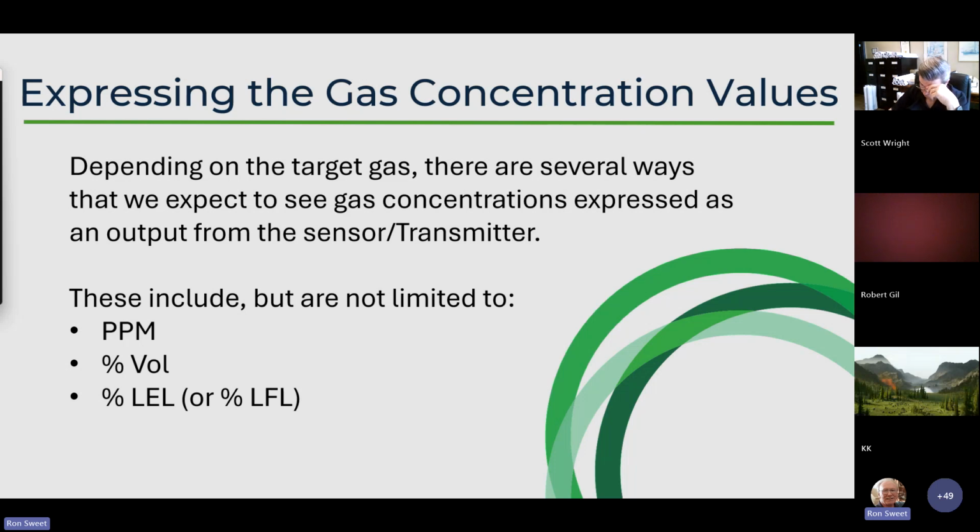So monitoring toxic gas buildup, for instance, carbon monoxide, up to 25 ppm, nitrogen dioxide up to 0.5 to 0.7 ppm, various other toxic gases up to a very small parts per million, to bring on the ventilation and bring those levels back down to acceptable exposure limits based on ACGIH, NIOSH, and OSHA permissible exposure limits.